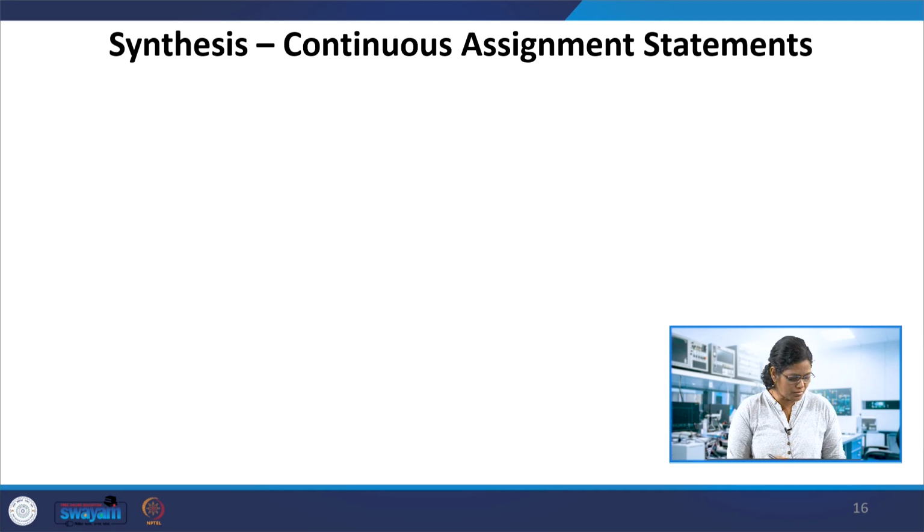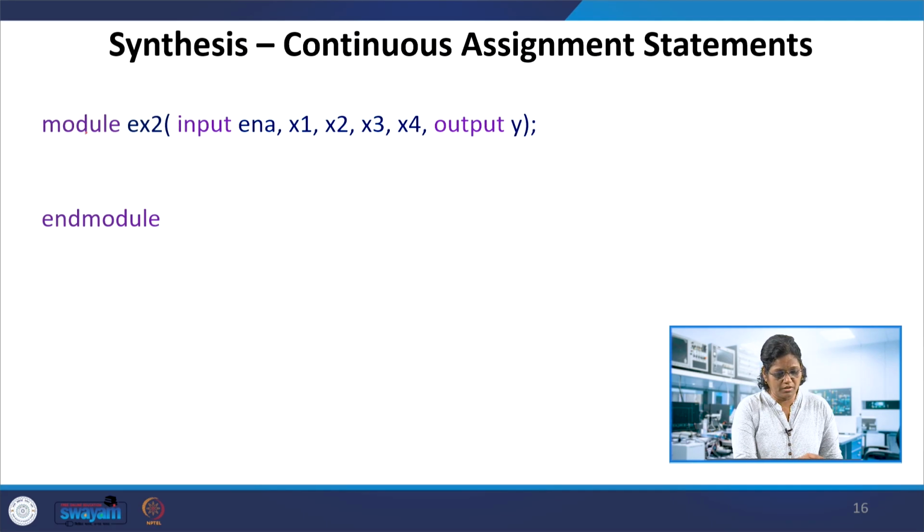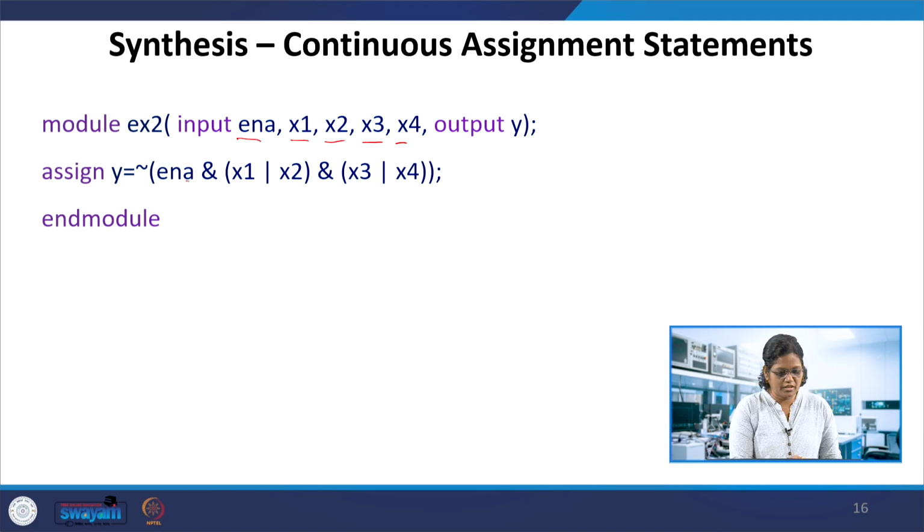Yes, it is synthesizable when the continuous assign statements are used. For example, module X with input enable, x1, x2, x3, x4. This is another example which has 5 inputs and 1 output, including enable as an input, and assign y equals enable and x1 or x2 and x3 or x4. So how is this getting into the synthesis process, how is it getting synthesized? The assign statement is synthesizable, that is, continuous assignments are synthesizable.